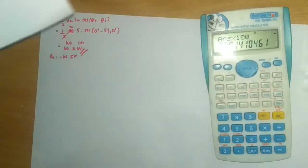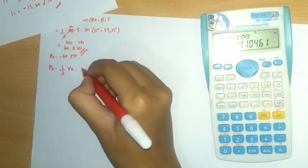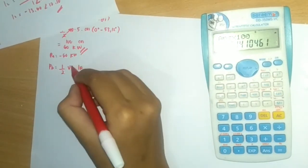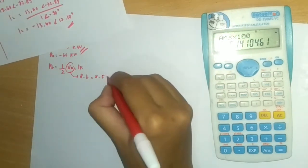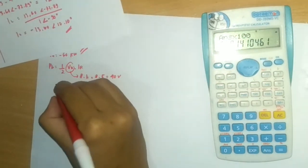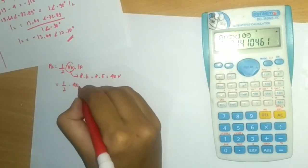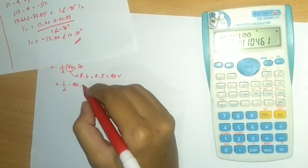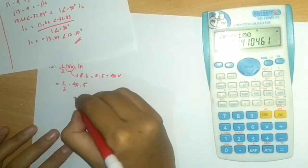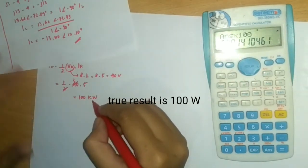The second component is a resistor, so PB is 1 divided by 2 V resistor multiplied with I resistor. We know the V resistor is 8 multiplied with I1, which is 8 multiplied with 5. We got 40 volts, and we got 1 divided by 2 multiplied with 40 multiplied with 5, and we got 100 watts.